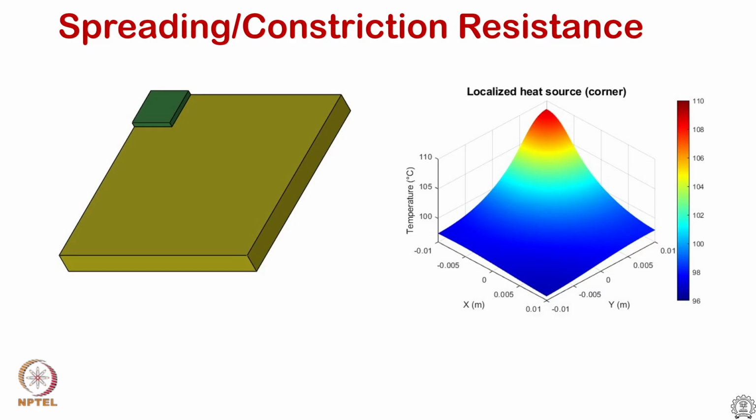Usually the hope is that the heat sources are located in such a way that the airflow is in a position to pick up heat from one source, and there may be multiple sources. As you can see in the laptop example I showed before, there are multiple devices: the memory device, the solid state device, the optical drive, and the processor, GPU, you name it, and all these devices are dissipating heat. There is usually a hub. Each heat source is going to heat up the airflow, and that hot air will make contact with the next heat source it comes into.